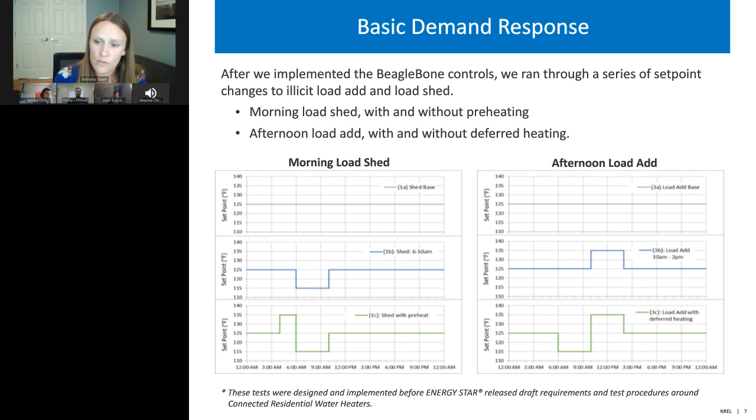I'll mention that we chose the morning load shed instead of what you might expect, an evening or late afternoon load shed, because we thought it would be more difficult. We really wanted to investigate the question of, can you provide load shed in the morning when people are taking showers? I think this is what Doug called his winter case, without affecting comfort. We thought that was a little more challenging from a performance perspective.